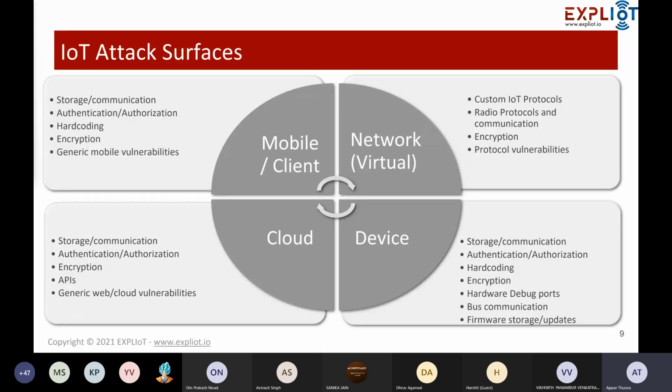So let's say you find a UART debug on the device. It can be interesting to see whether it has authentication on top of that, or whether it is just an open hardware debug header. Then hard coding. Hard coding comprises hard coding your keys and certificates onto the device, which is again a very common practice that we find on a lot of devices that we come across.